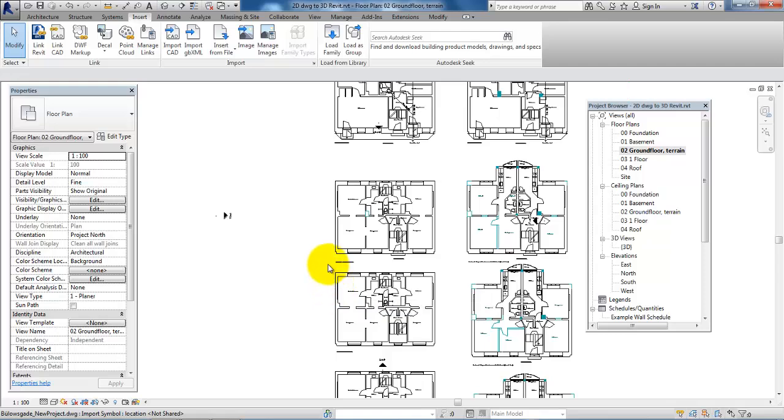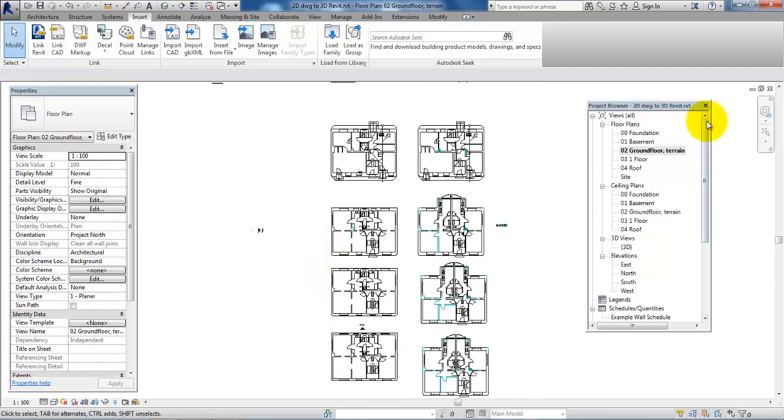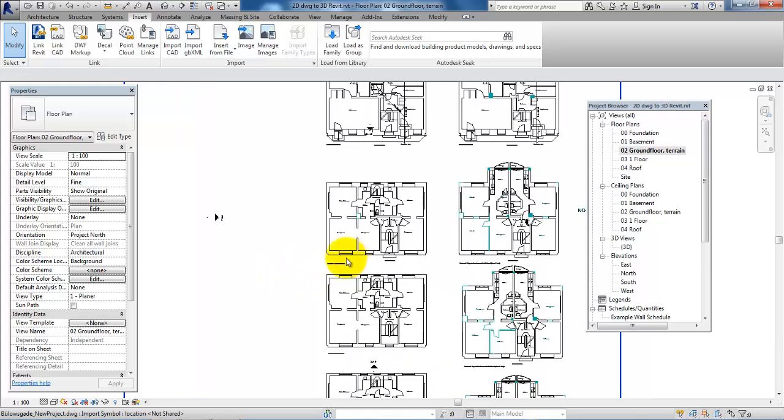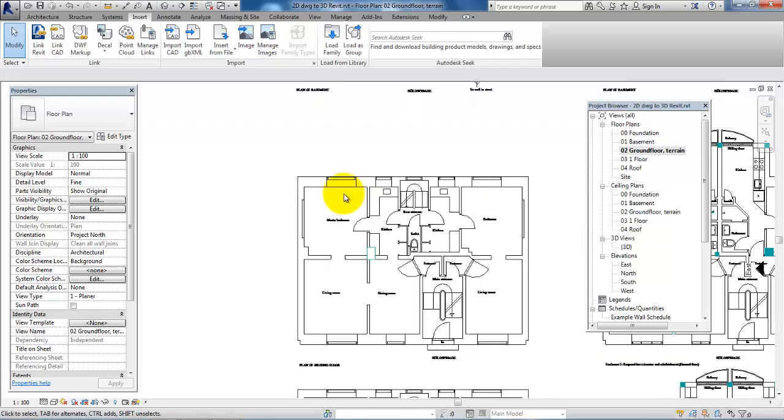And in this case we have a multi-story building. So at the moment I'm at the ground floor, and now I want to draw the ground floor, which is this plan right here. So first I need to know the dimension or the thickness of the external wall. And in this case we have 590 millimeters, and the gable walls have a thickness of 350 millimeters.